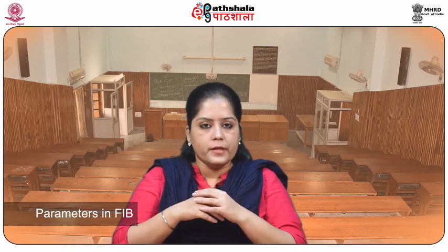So students, let us now discuss some of the parameters in FIB. The ion beam source is a liquid metal ion source, especially gallium ion sources. The acceleration voltage of ions is typically of the order of 1 to 50 kilo electron volt. The resolution of the feature size is better than 10 nanometers.